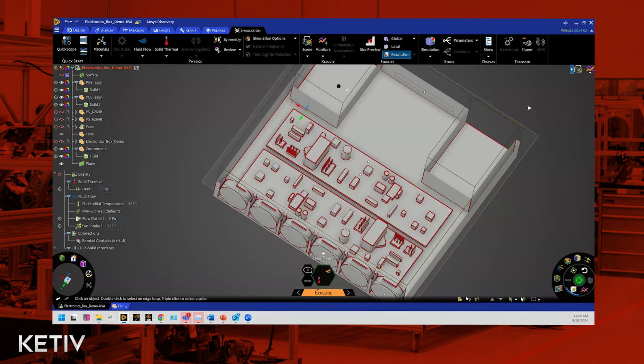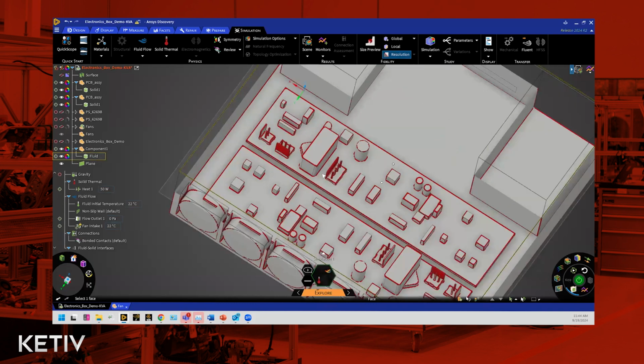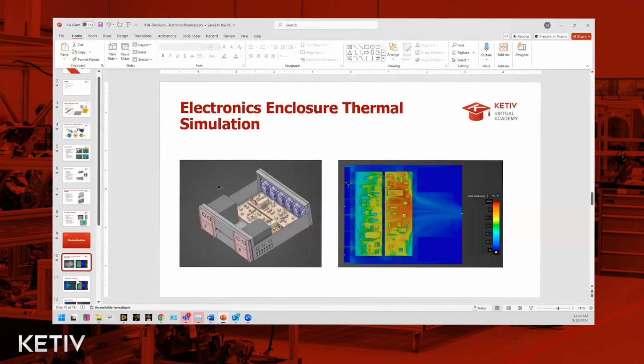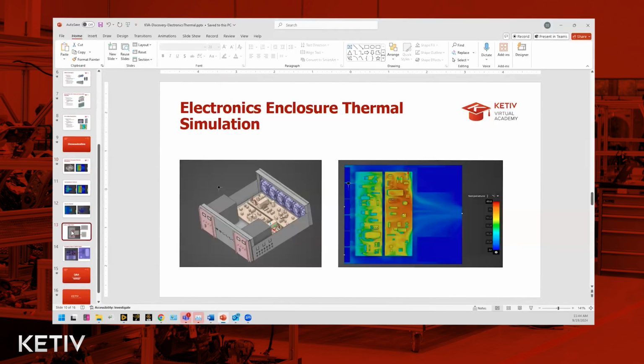So that means that in the bulk zone, that is the smallest mesh resolution that you can get. So what if you have a feature that's smaller than 1 millimeter? And those are the regions that are not being resolved accurately, right? So if you turn on resolution alongside a cut plane, you can actually see which regions are not being resolved. They're highlighted in red. They have a very coarse mesh around it, okay? For the sake of saving time, I have a slide that shows what I'm talking about.